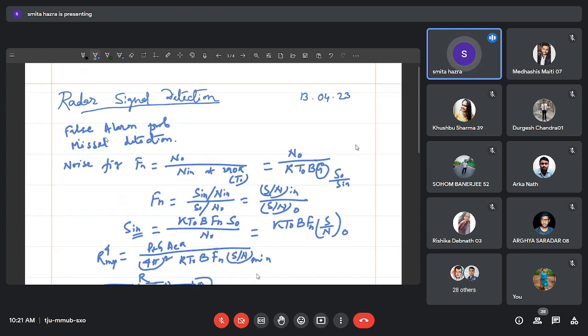The problem of the false alarm is when there is no real signal, only the fluctuations of the noise create the exceeding of the threshold. Clear? What is the problem of the false alarm? It is when the fluctuation of the noise becomes so high that it exceeds the level of the VT. Actually, there is no echo signal or extra component from the desired target or from the real object. When this happens, we are led to the false alarm probability.